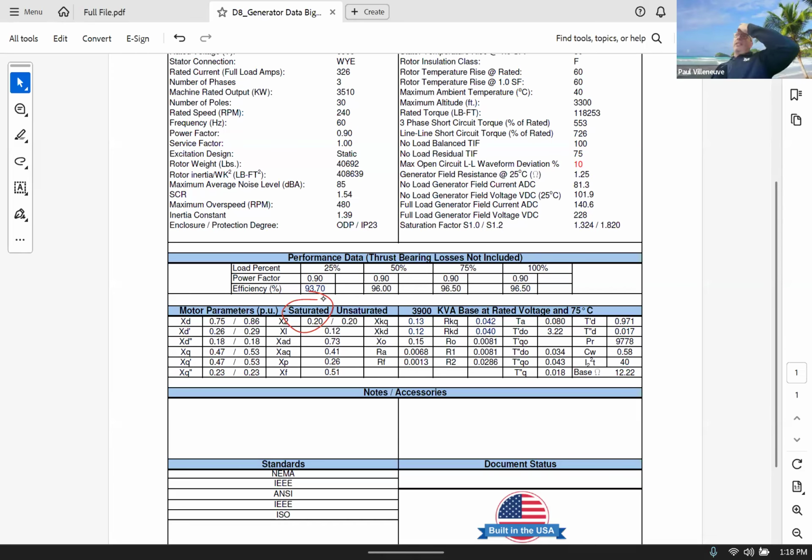So that's pretty common. Like if you remember the data sheet when we did the test, we needed to get the X values for the R equivalents, RCs, all those. But that was 60, 80, 100, I believe, was the rating for that. And so that's pretty common for bigger transformers. You have multiple ratings on it. That just means you're putting some sort of cooling mechanism in there.